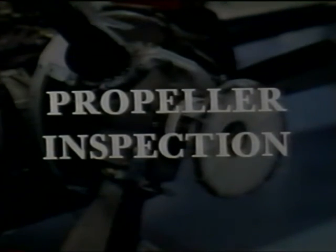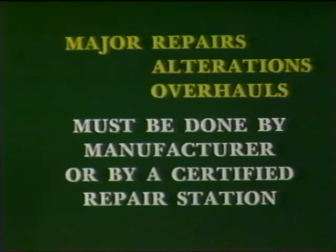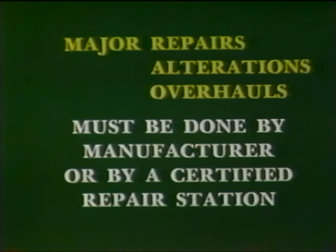The inspection, adjustment, installation, and minor repair of a propeller and its related parts are the responsibility of the powerplant mechanic. The powerplant mechanic may also perform the 100-hour inspection of the propeller and related components. Major repairs, alterations, and overhauls of propellers must be done by the manufacturer or a certified repair station.